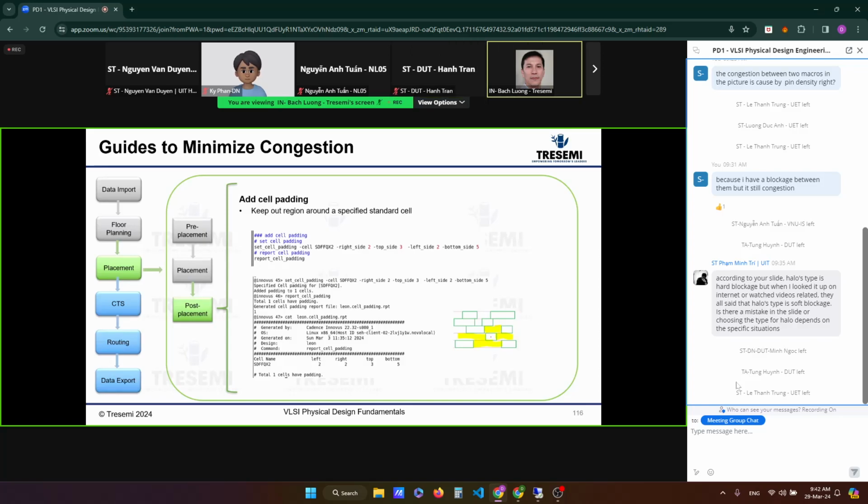Right? So in your labs, you may have congestion and you have to know how to resolve it. In that lab, I purposely didn't make it super clean for you to see what's happening, and you use the skills you learned to resolve it. You'll see some of the things that I left at default, and you should be able to see, oh, it shouldn't be here. If you pick up all the concepts from floor planning to placement, you should be able to pick out that this shouldn't be there, this could be an issue, and so on.